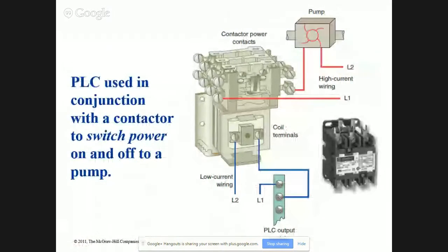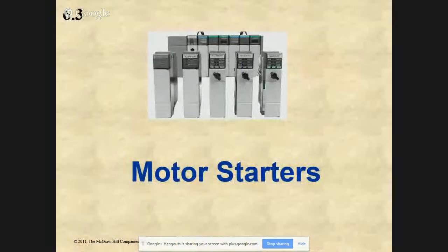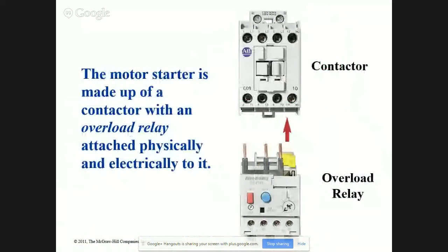Here we have contactors. We have motor starters. I want you to pay attention. We talked about overloads and feedback. If you're going to wire a contactor to a PLC, eventually it's going to trip. It'd be nice if the PLC knew that. Depending on the operation, if it's a linear conveyor system and you've got conveyors 1 through 10 and number 5 trips, what happens? It's a big mess. So down here on the overload relays, there's a couple of options.